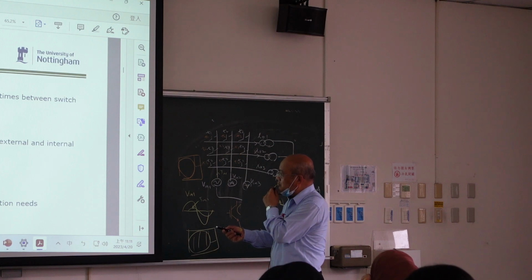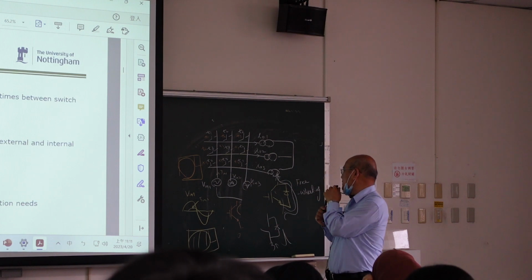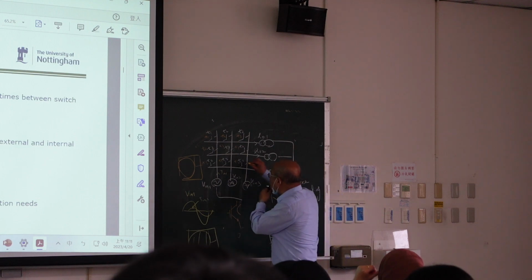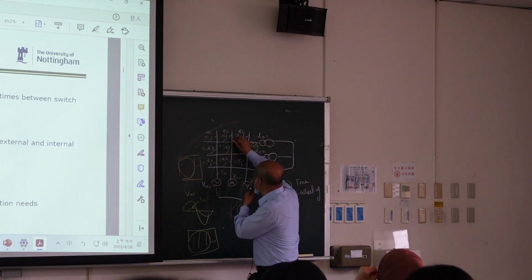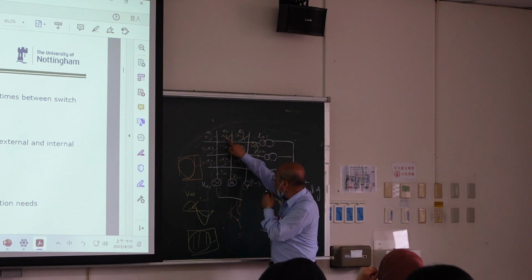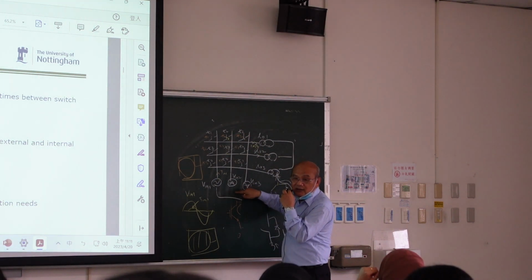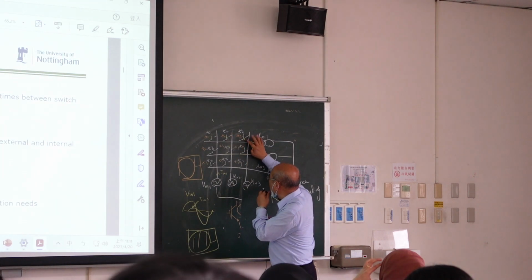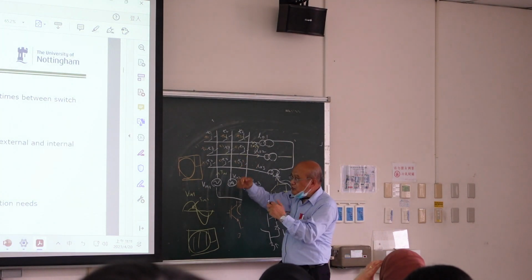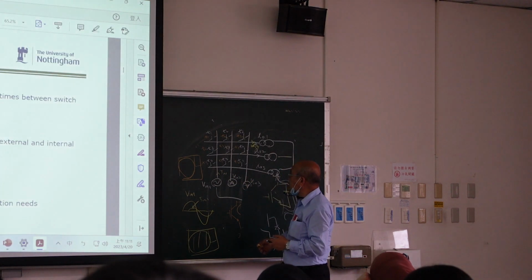And we have to design current commutation. We will discuss later. What is current commutation? If you have current here, 10 ampere, originally this one turns on, then this one turns off. If this one is not turned off, this one turns on, then short circuit, right? If this one is already turned off, this one is not turned on yet, then open circuit. Now you need to keep 10 ampere. You need to avoid short circuit. What can you do?